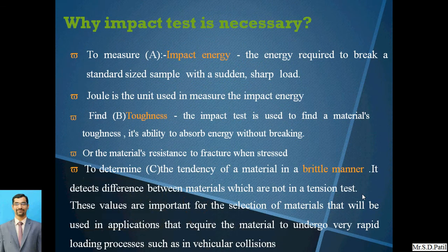Now, why is the impact test necessary? These are the reasons. First of all, to measure the impact energy, the energy required to break a standard sized sample with a sudden and sharp load. So we have to analyze how much energy is required to create the failure in the material. We will get that energy with this test, how much energy the material is able to absorb. Joule is the unit for this impact energy.